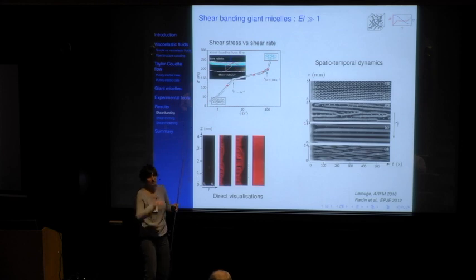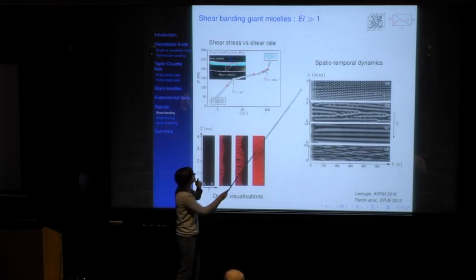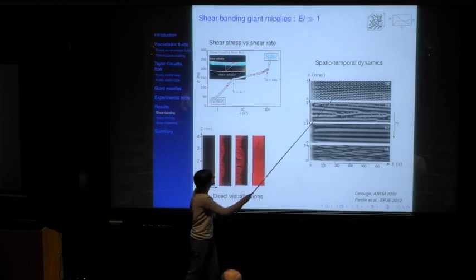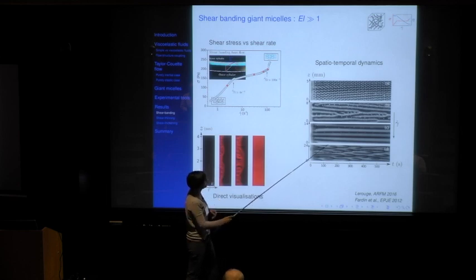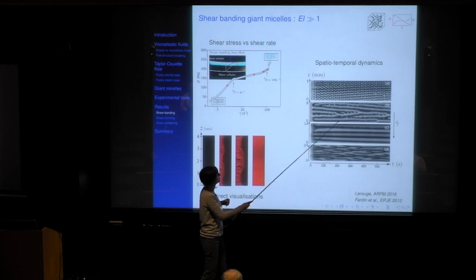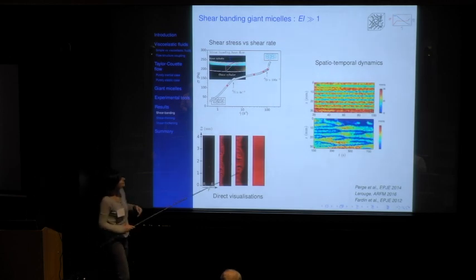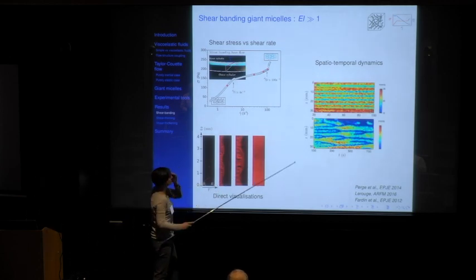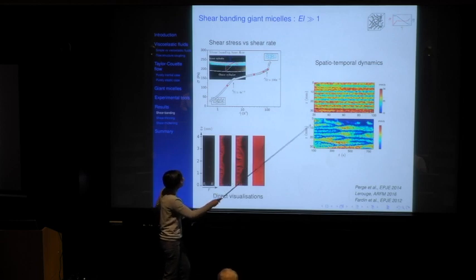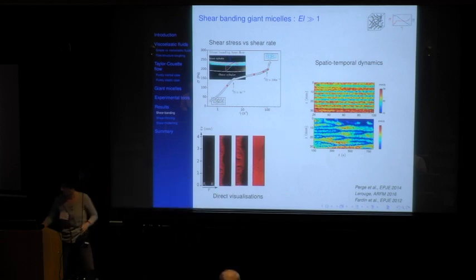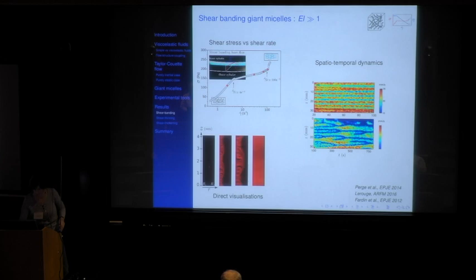It consists in plotting the interface profile in gray level as a function of the z coordinate and the time, and we observe a zigzag pattern, then a pattern of creation and annihilation of pairs of vortices, a stationary pattern, and again a pattern of creation and annihilation of pairs of vortices, but opposite to the first one. We can obtain quantitative information using the velocity field, and we can also follow the flow dynamics using the velocity maps gathered as a function of time.